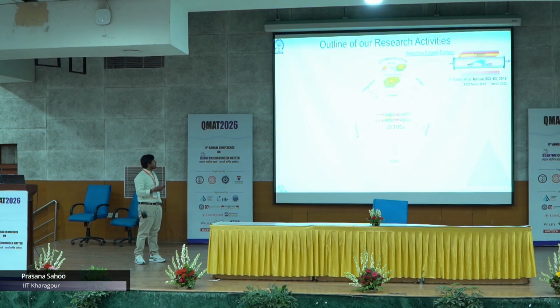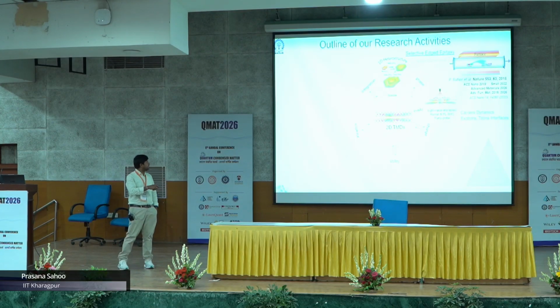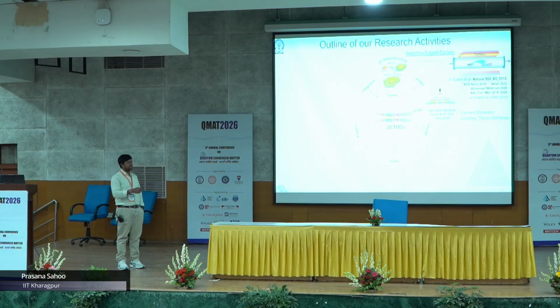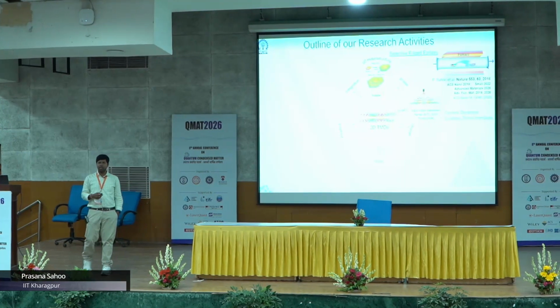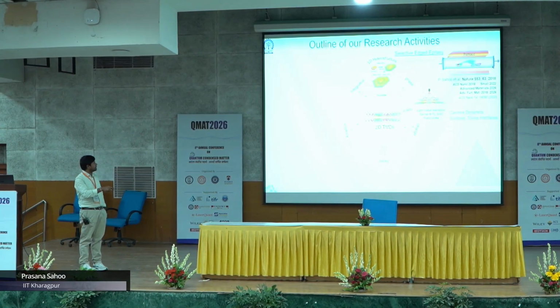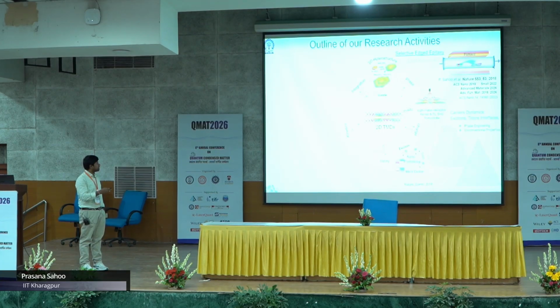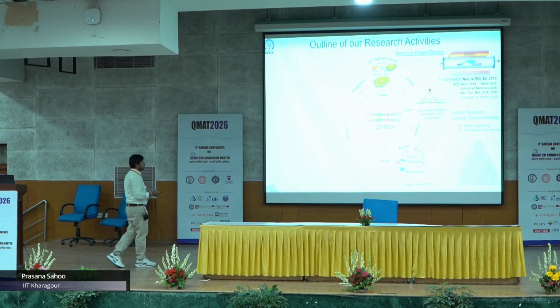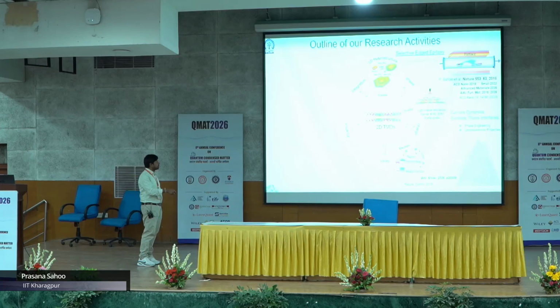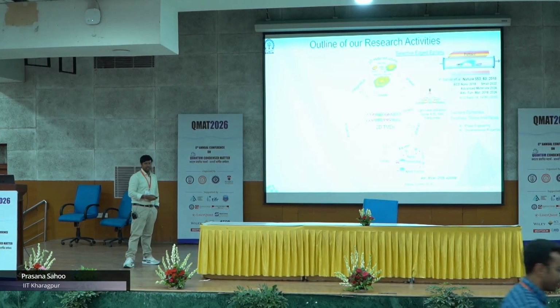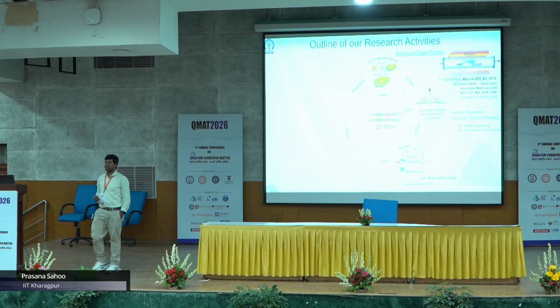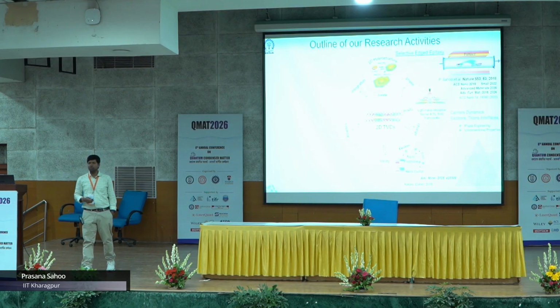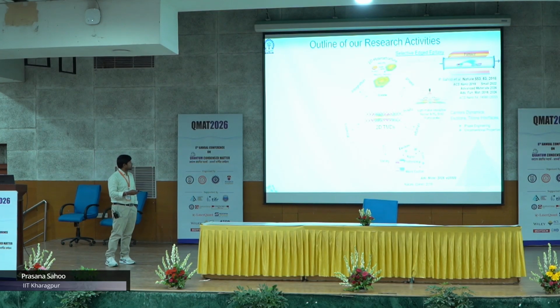Before going to that, our work involved mostly fabrication of this kind of lateral engineered structure. We can create a PN junction using a simple CVD method. We can definitely control the number of widths. And the second recent work I will show at the end. So you can start different sets of lateral heterostructures. You can see multiple exciton, phonon, and second harmonic generation modulation, and how we can tune it using this combination of structures.